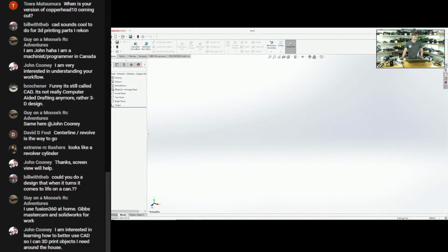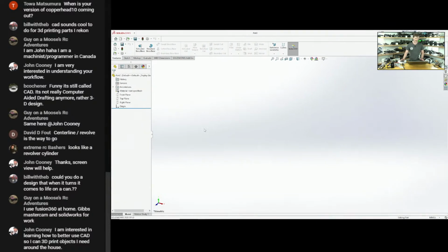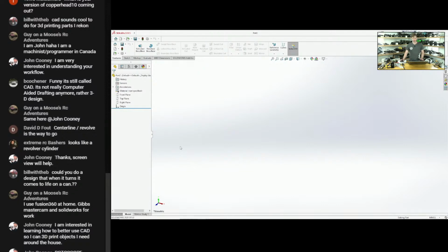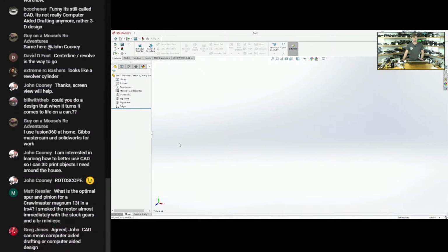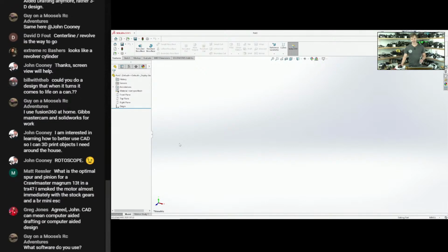All right. So if you were looking to 3D print objects, it's a completely different workflow as compared to machining a process. What I'm going to show you today is going to be a machined product, in particular on a lathe, or what would be considered a machining work center lathe. So this is going to be a lathe that not only has turning functions, but it has drilling and tapping functions, has live tooling on there. This would be the X direction, so if we've got our object being turned,